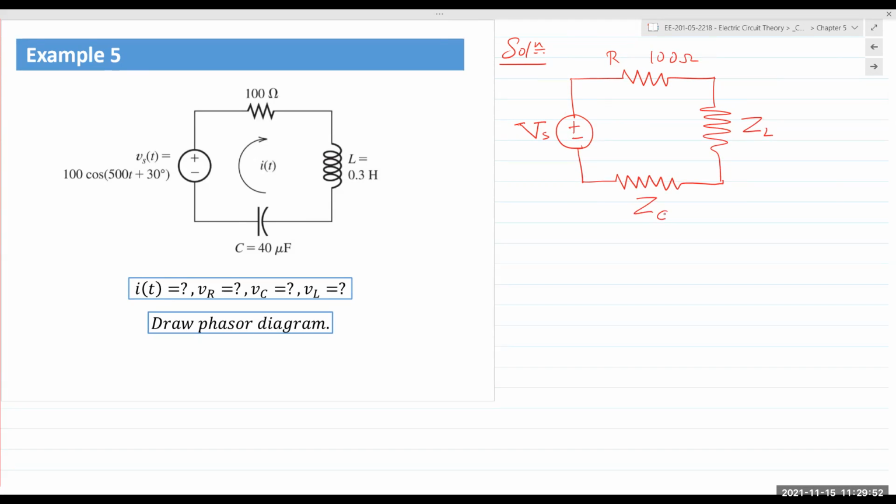So now, if you don't look at the notations, what do we see? We see 3 resistors all connected in series. And if you think back to chapters 1 and 2, this is something you've already done. Applied Ohm's law, KCL, KVL, resistive circuit analysis, reducing a large network of resistors down to one single resistor and simplifying from that point on. And that is exactly what we're going to do, except the math is now with complex numbers. That's the only difference.